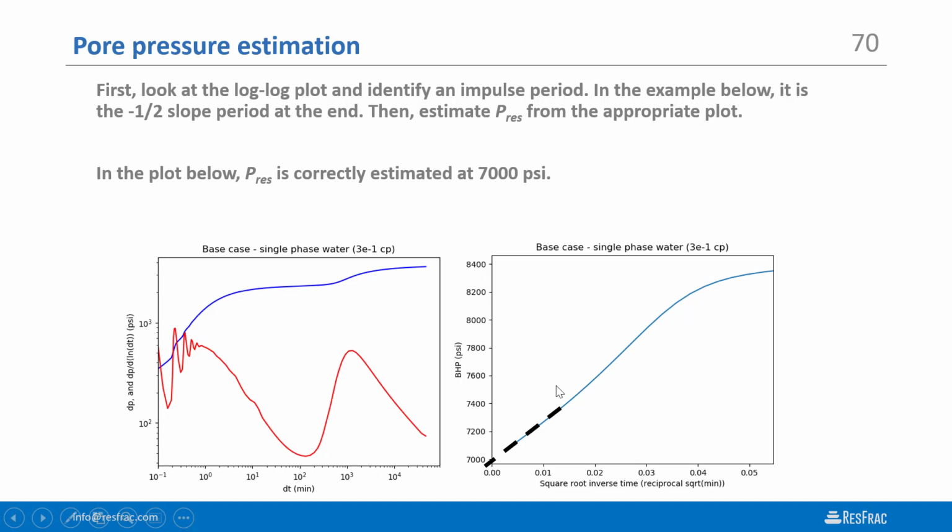It doesn't matter how much you inject. If you hit hydrostatic, that's still gonna kill you. And I've seen field tests where they don't get out to impulse in time and they hit what you might call vacuum at the wellhead. That's a frustrating problem. The only ironclad solution to that is to use a downhole shut-in tool. Of course, that itself is expensive and is not that common, but it's possible to avoid it, but that's the solution.